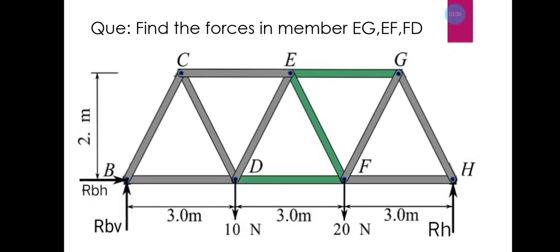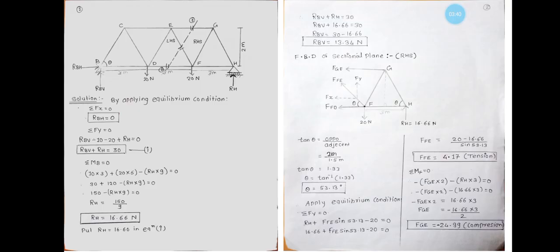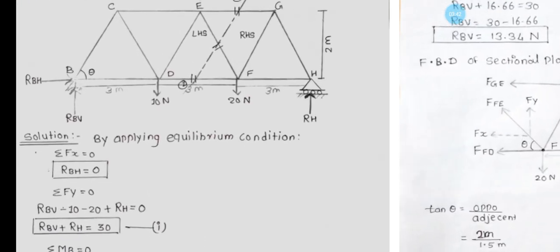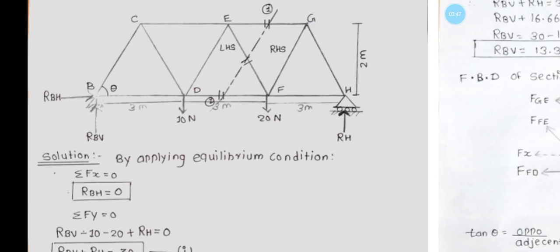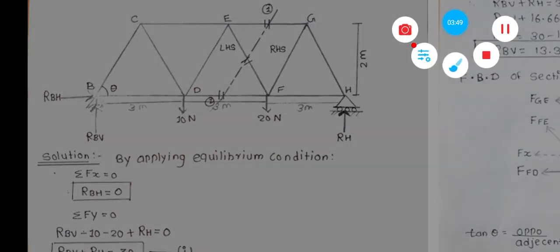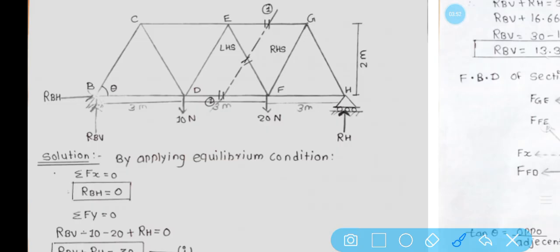So see the solution of how we can calculate the forces in members. Here is the given question. First you draw the given structure of the trusses and mark the members in which you want to calculate the forces.